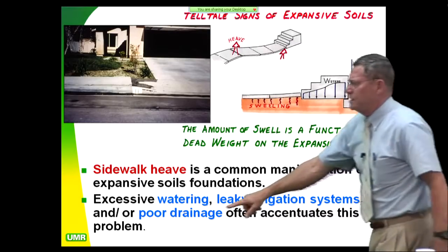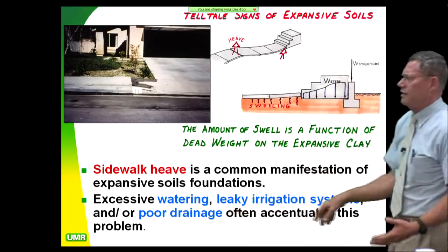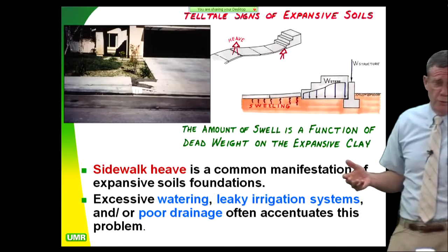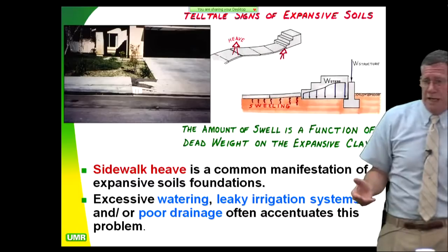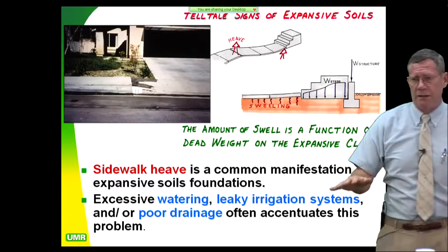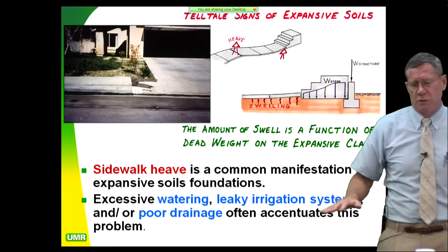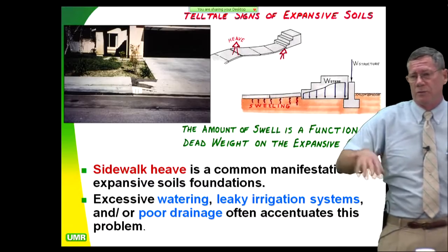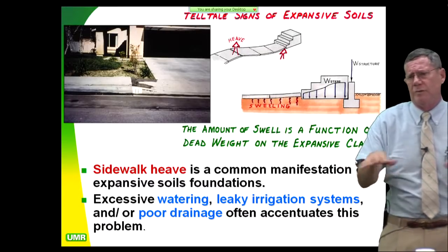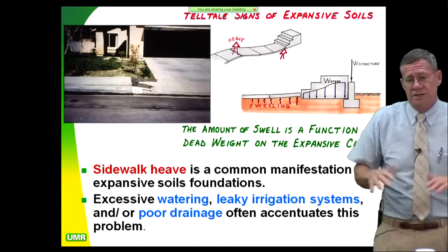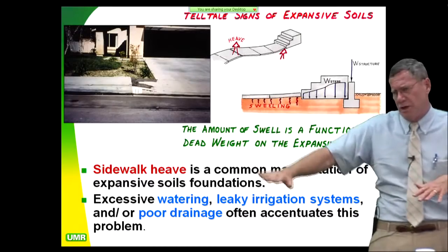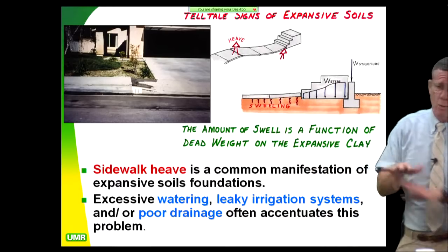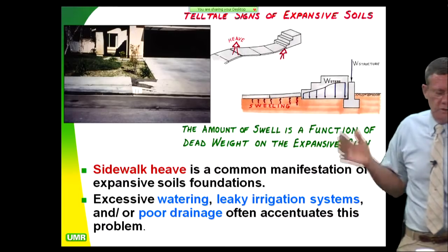The other thing is poor drainage. If you have some area that has poor drainage, you're going to have problems. Now, a lot of people don't start with poor drainage. They get poor drainage because of landscaping, because of the ground lifting up a quarter inch to half an inch a year, with root activity, root biomass, and worms. So what used to be a 3-inch depression next to the house, 20 years later it's gone, and you've got water ponding along there, even though it wasn't graded that way.